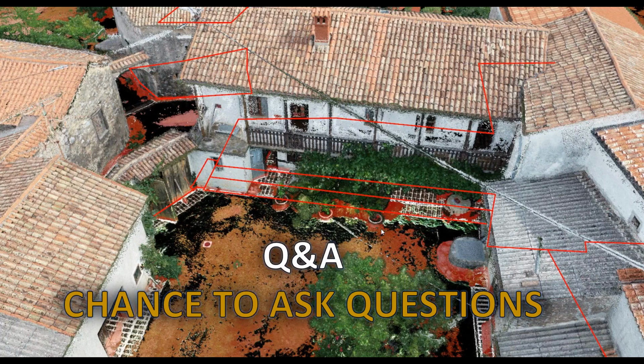Even with total station, we usually measure the building corner at ground level. So the mesh in this case only gives us the altitude of the corner. So for 2D, it will be in grid. So it will be, if the building is perpendicular, it will still come out perpendicular.